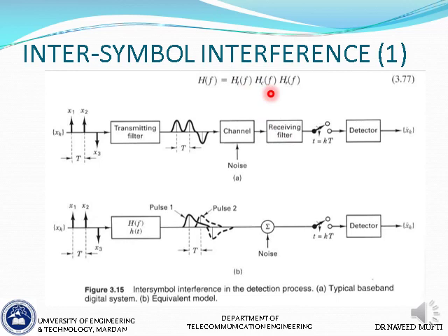ठीक है, तो ये जो हम रेक्टेंगुलर पल्सेस ट्रांसमिट करेंगे, the rectangular pulses transmitted, they will arrive at the receiver without distortion only if the channel has infinite bandwidth. जबकि रियल में क्या होगा, a typical rectangular transmitted pulse of duration T will arrive at the receiver with non-zero rise time, non-zero fall time because of filtering, and because of the fall time the pulse will spill over into the following symbol interval, and this will cause interference between symbols, adjacent symbols, और इस इंटरफेरेंस को हम फिर ISI कहते हैं. ठीक है, सो दिस इज़ द बेसिक कॉन्सेप्ट ऑफ ISI. तो नॉइज़ हो ना हो ISI हो सकती है.